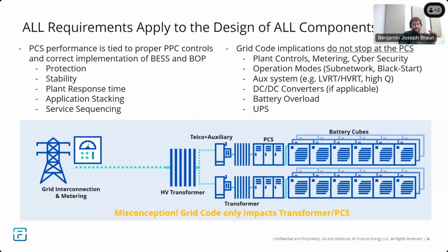Protection considerations: if my inverter is now a voltage source rather than a current source, if it's maybe even providing a heightened amount of fault current, I have to make sure that while providing that to the grid if it needs it, I also still protect my own internal equipment if I happen to have a fault somewhere.